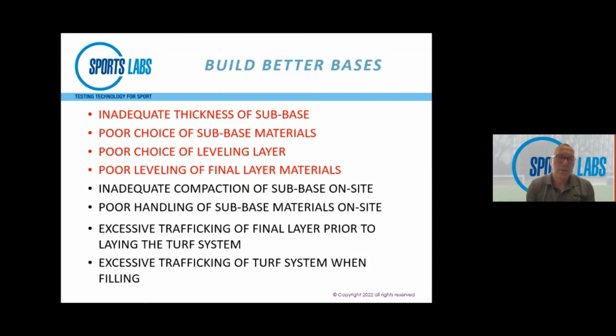If you're using a leveling layer, which normally if you've got an angular crushed rock, you will do, it's got to be compacted well into the surface of the subbase material, and it can't be too thick because you will leave marks in it. It will move around. It may even cause porosity issues itself. And then poor leveling of the final layers, that can be with roller marks, footprints, etc. That just makes the carpet installers, turf installers' life a misery.